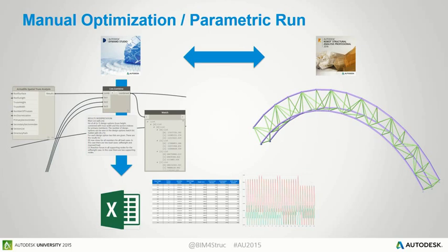It's finding a ratio. So the ratio is the actual stress divided by the allowable stress. If the ratio exceeds 1, then add that big penalty weight on it. If the ratio is lower than, for instance, 0.8, then I have an over-designed member. So that should be a better way to find another solution for that one. So there is also a penalty weight, but the penalty weight for the minimum, let's say for those ratios lower than 0.8, is a very low penalty value. And the reason for that is I thought it was much more important to avoid overstressed members. You always have over-designed members in a structure.